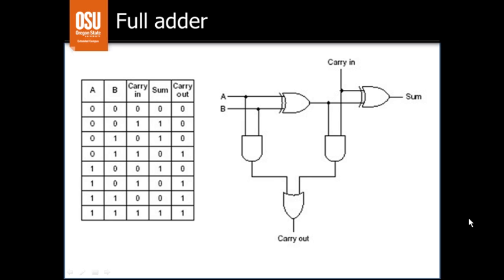Now, if you split the circuit up a little bit, you can see where both of these circuits are developed. Although these circuits were developed independently, we can integrate them into one circuit. In the top part of this diagram, we have A and B, and let the carry in be C. Then you have 2 exclusive OR gates to produce the sum bit, which is exactly what we did in the previous lecture. Similarly, you can produce the function for the carry out bit, and you do that in the same way that we produced the circuit for producing the sum bit from 3 inputs.